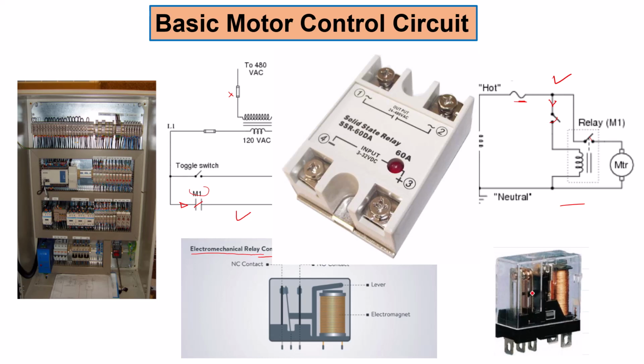Basically, the electromechanical relay has a maximum number of switching operations it can perform before it starts to wear out. On a data sheet, they will tell you, for example, that this one can switch 100,000 times. Click, click, click. After 100,000 switchings, the relay contact will wear out, or they will tell you there is no longer any guarantee that it will continue to work as expected. Maybe there will be a high impedance that increases the power losses, because it's not going to be a very good, effective contact.